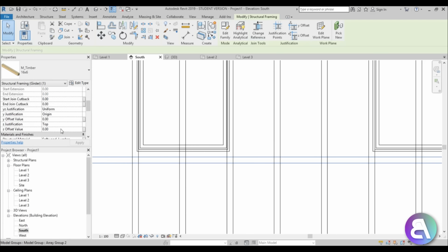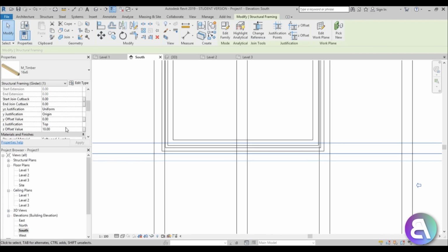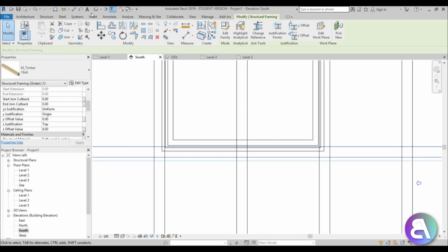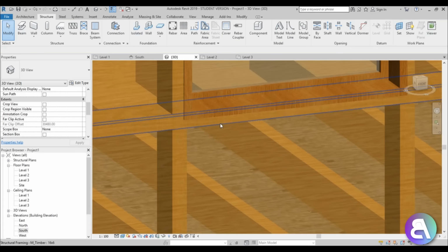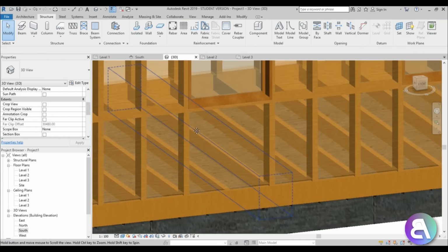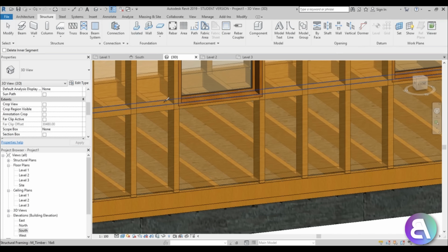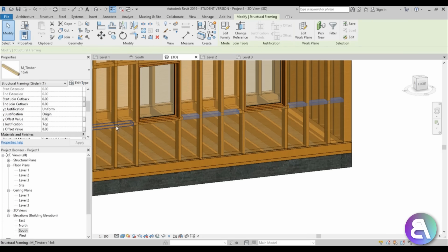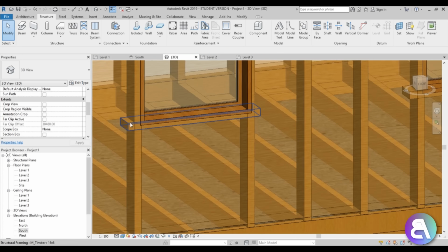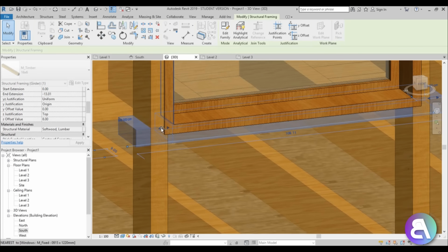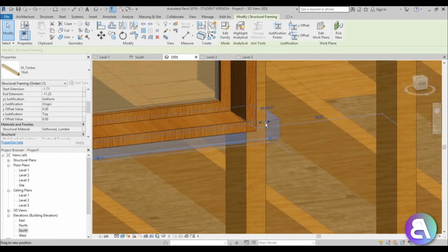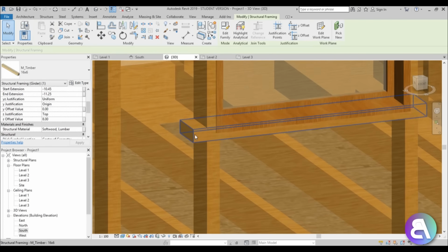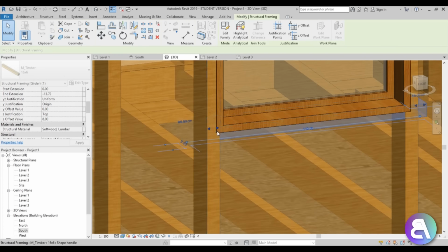And let's just do a Z offset for this one. Let's try 10. Okay, a little less. Let's try 8. Yeah, I think this works. If we just zoom in here, yeah, this works perfectly. And now you just go with SL for split element, and you split it here, split it there, split it here, split it there, and you delete everything you don't need. So you select all of these, delete, and then you can just select this and move it inside here, and do the same thing here. So you've got your framing construction for your windows.